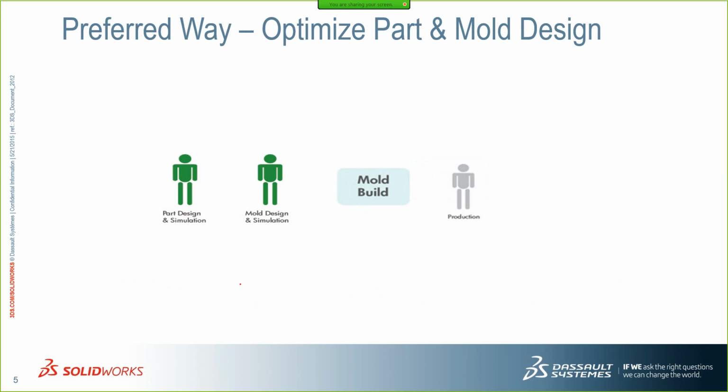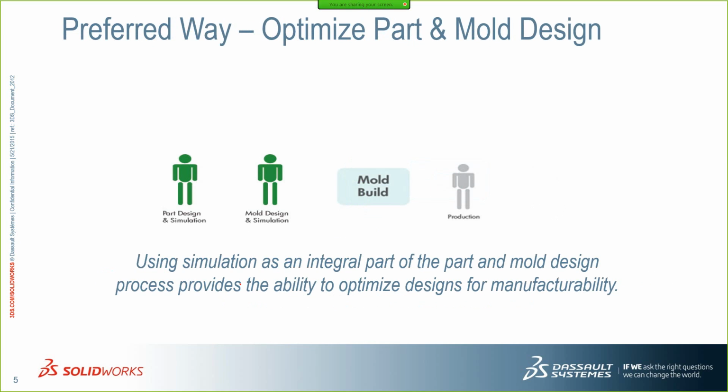And finally, the preferred way, the one that we are proposing and discussing today, is this one, wherein I design the part and I simulate. The simulation I am talking about here is simulating the plastic injection process. I do many finer things over there so that I know this part can be manufactured in a certain way, using a certain material with a certain thickness.